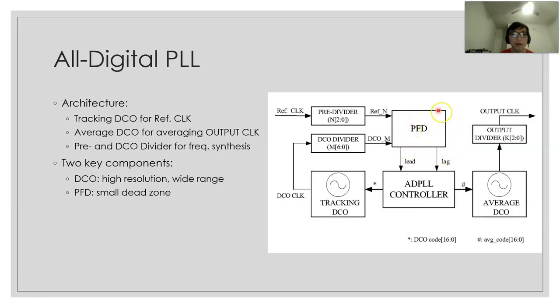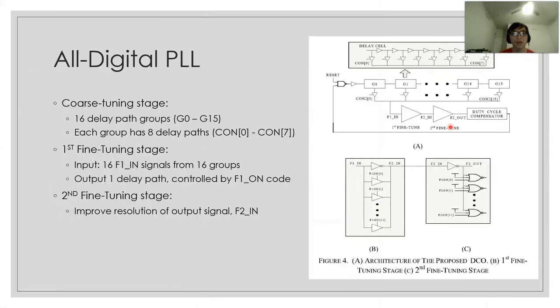Alongside that, the PFD, the phase frequency detector, also needs to be designed so that it has as small a dead zone as possible.